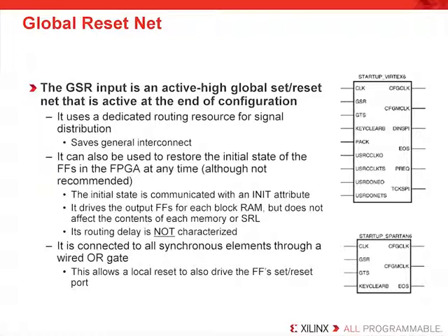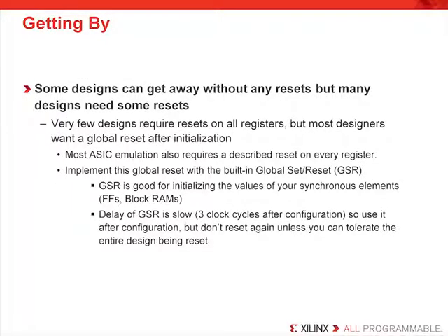Now, this is connected to all synchronous elements through a wired OR gate, and this allows a local reset to also drive your synchronous elements in the FPGA and not just reset with the GSR. So both are supported. Some designs can get away without any resets, but many designs will need some resets. Very few designs require resets on all the registers in the FPGA, but most designers want to use a global reset after initialization, and that's what the GSR should be used for.